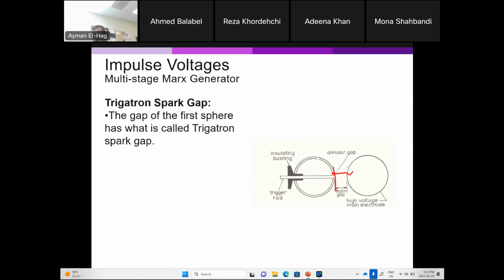So we increase the voltage here, and we said that for the flashover to happen on the arc, it depends on the availability of the electrons. Now, when we trigger this, we are ensuring basically that this will trigger because we have high voltage and a trigger switch to generate those electrons, then you will have the flash.